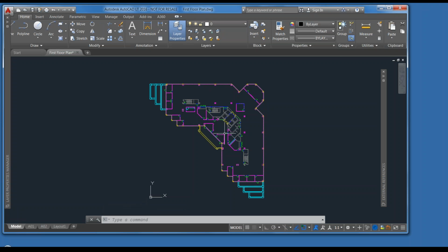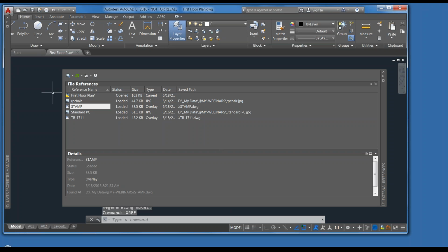Okay, so back in this drawing, we're going to discuss a little bit how to break out the drawing into more useful X references. So in this case, we just see the basic walls and architecture of this drawing, but we could do the structural grid separately. So I'm going to bring in a structural grid that I have as a separate drawing.